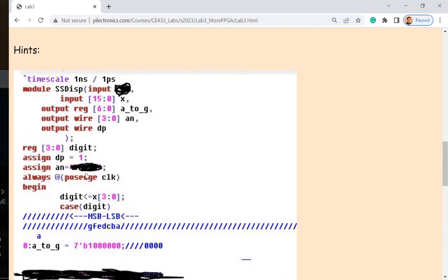And this is a module, right? So this is an example of a module, the display module. And this one is not updating that activation bit. If you just look at the input and output, wait, is it updating that? Or do I still have an AN here? Oh, the AN just sets up an initial state for the activation. So for this module, it only receives the switch's input and sends out an output to the outside world. So we need a test bench here, which connects to the SEGs, right?